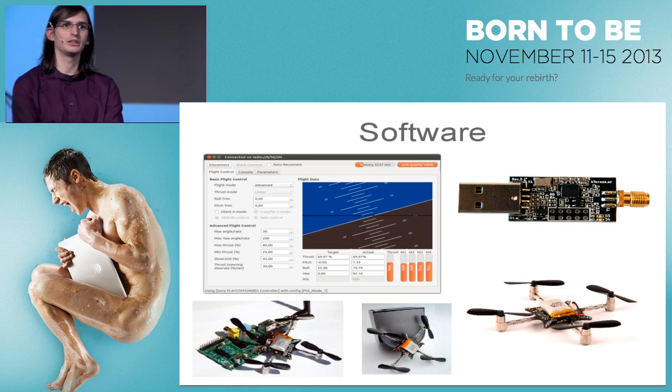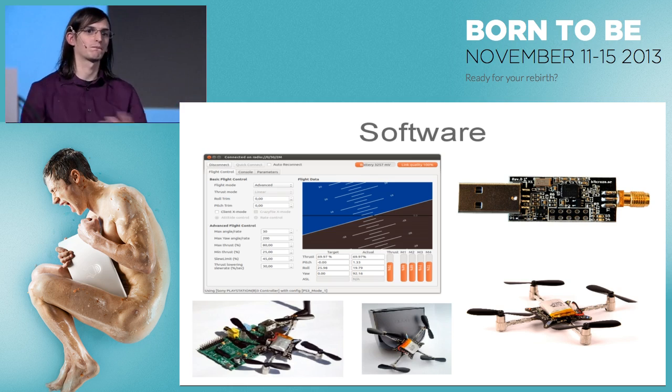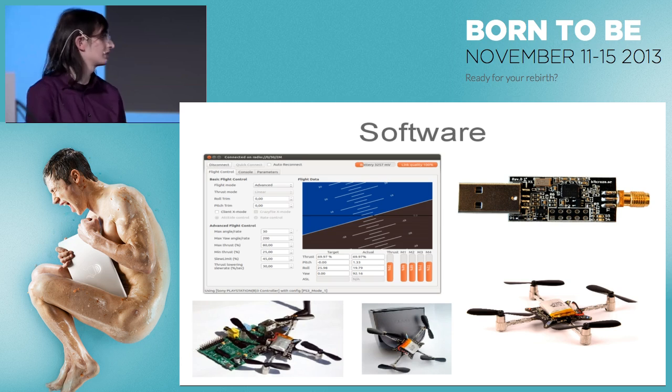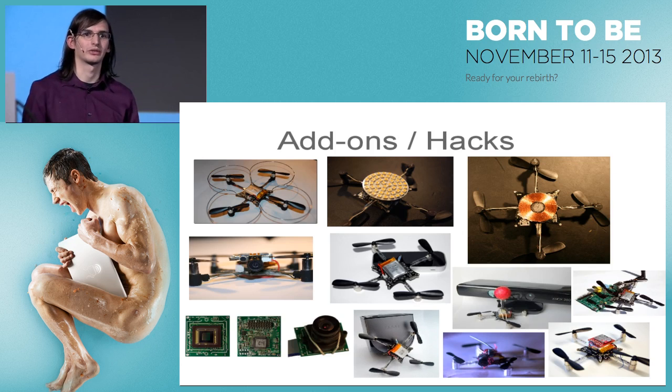And the chip we are using is not used that much. So all the tools were proprietary and all the libraries were proprietary. But it's a chip that's simple enough. It's 2K of external RAM and 256 bytes of RAM in the CPU. It's an 8051. It's so simple that we could do the programmer, all the libraries, all the drivers for it, and the USB stack. So this is running only our stuff.